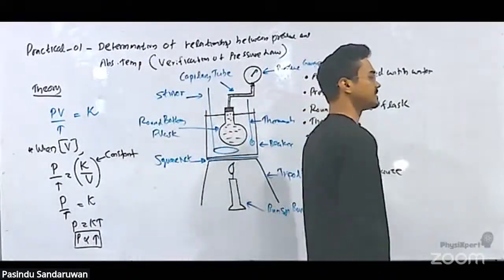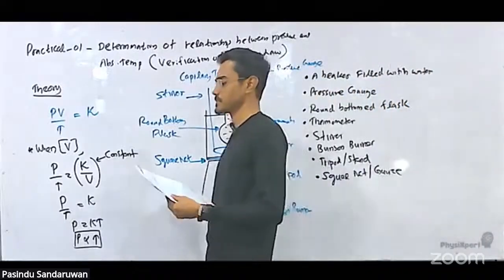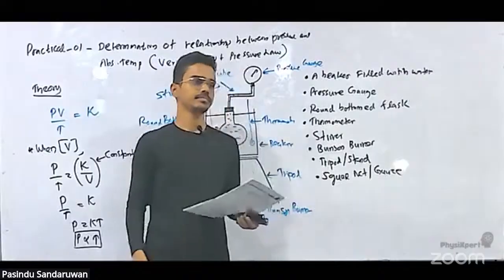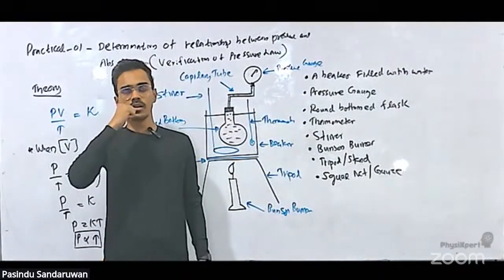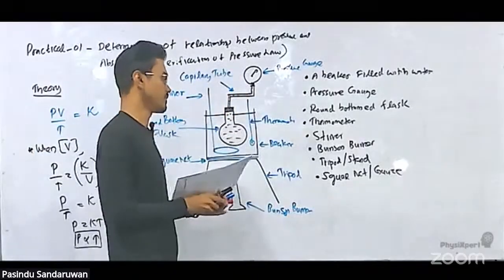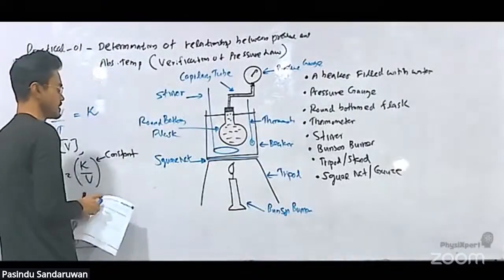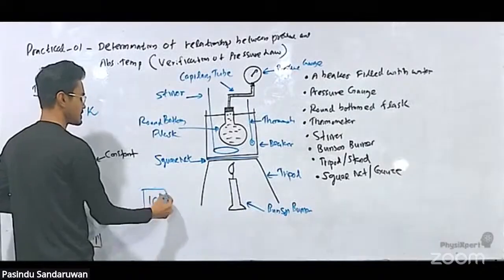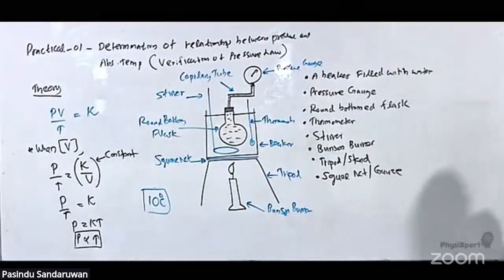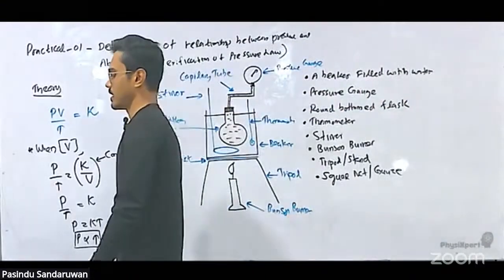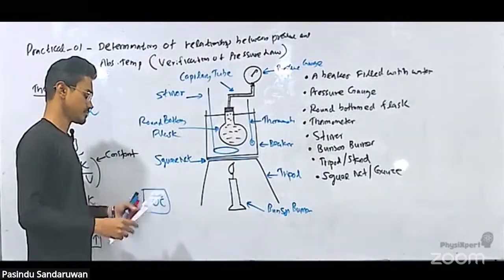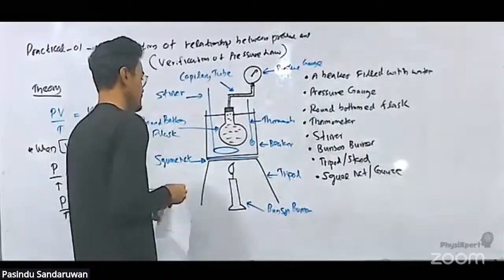Record the pressure from the pressure gauge when increasing the temperature, for each 10 degrees Celsius, and record them in the following table. It is not a big table.